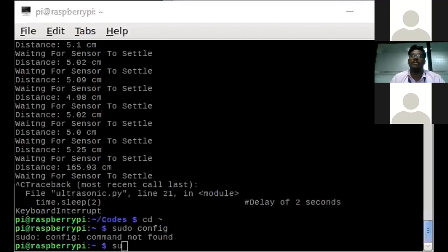Then the PIR sensor, the passive infrared sensor, is used to detect the motion of an object. A still object can't be detected, which is a limitation of the PIR sensor. The IR sensor is used to detect objects whether the object is in motion or stable, we are able to find it. But a black object can't be detected, which is a limitation of the IR sensor.